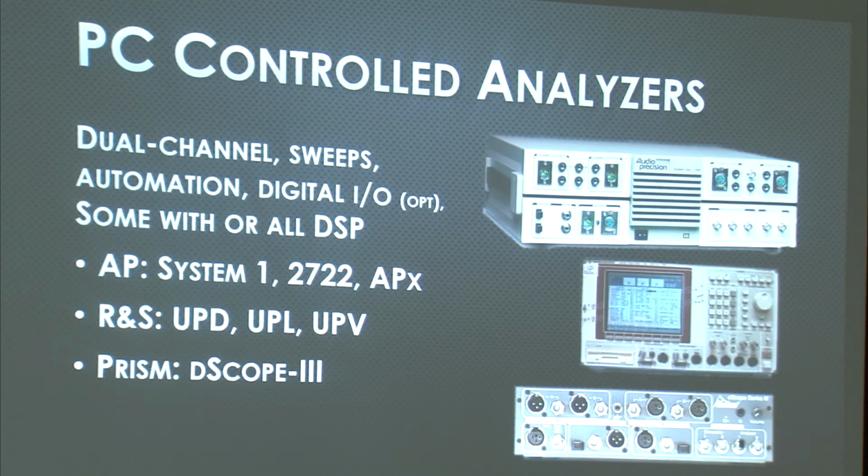Well, what they did before they had the distortion capabilities, they put some filters in there. So there's a 400 hertz high pass filter. You put that in there, and if your distortion drops, you know you had hum problems, because most of the hum issues are below 400. And so you could use different analog filters to try to see where your problem was, but you know, it was hokey. To put it mildly.